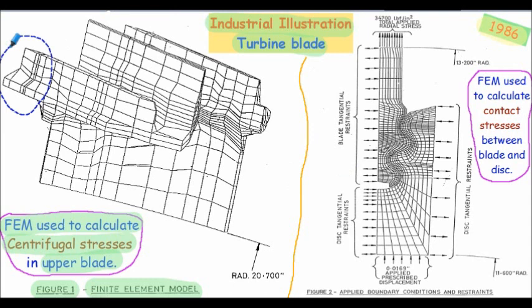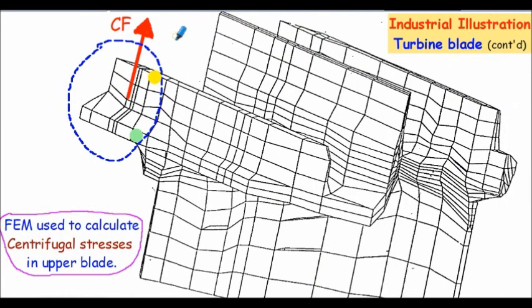And this particular check relates to this location of the turbine blade. So essentially the hand calculation we tried to undertake was to use classical bending theory to evaluate the stresses shown here and here on this section of the turbine blade, due to the centrifugal force of this portion of the turbine blade generating a bending moment about this section. So quite a crude calculation, but we're just trying to ballpark these stresses to see if the model results were producing stress levels of a similar value.